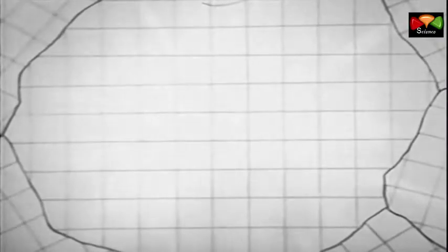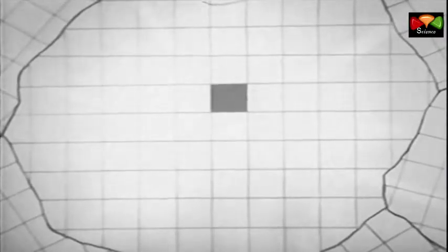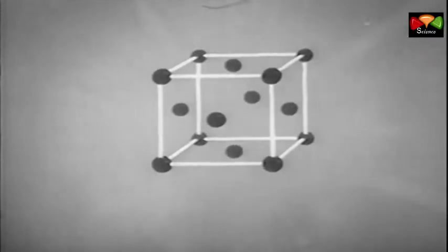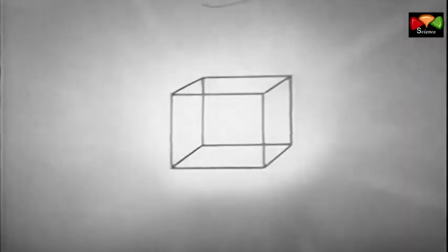Microscopic study of a cross-section of an aluminum alloy specimen reveals a network formed by the boundaries between grains of the metal. Each grain is an accumulation of individual crystals or unit cells. The single crystal or unit cell is conceived to be cube-shaped, with atoms of the metal arranged in regular order, one at each corner and one in the center of each face of the cube. These unit cells combine to form what is known as a space lattice.